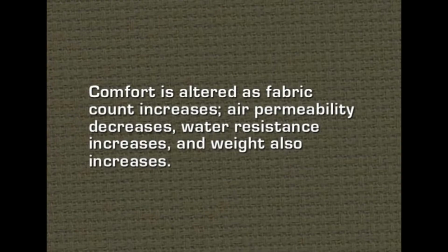But comfort is altered as fabric count increases. That is because the spaces are closed, and so the air permeability decreases, and then the water resistance is increased just because there are no interstices in between, and thus water cannot enter through, and naturally the weight is also increased due to that. Fabric shrinkage decreases with the increase in fabric count because there is no room for shrinking, and the flammability also is decreased because it will not be able to support combustion.